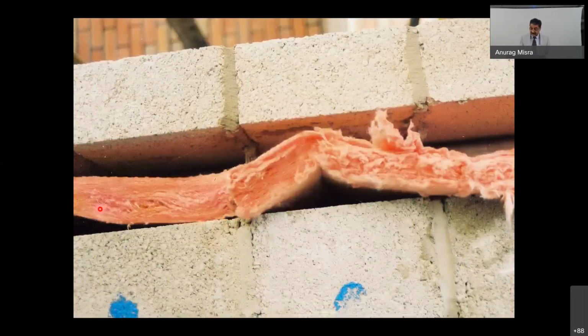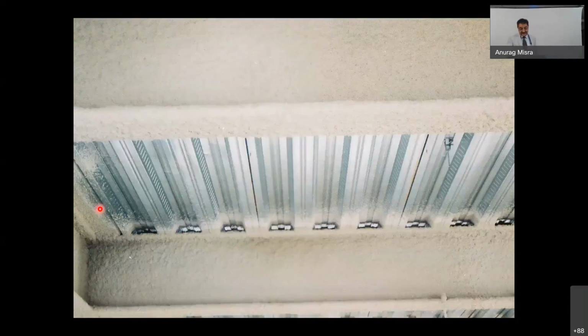This is another one that I wanted to actually discuss. Here you can see that these are steel buildings. Then this deck sheeting is used for concreting. Concreting has been done from the top side, and this steel building is actually shotcreted with a cement-based composite, which is providing you enough cover for fire protection.